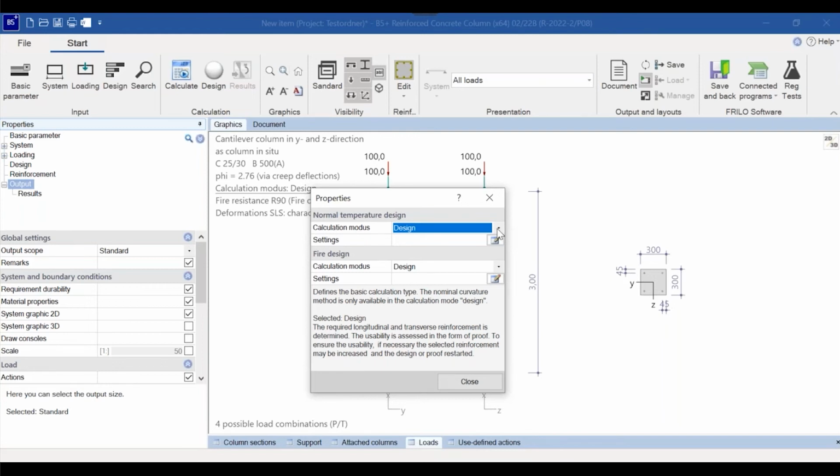So it will be recommended which reinforcement values we need for this kind of system and these loads. In the check part, it will be a little bit different. You will check whether the system is stable and balanced with the given longitudinal reinforcement. And the third parameter is the load factor.